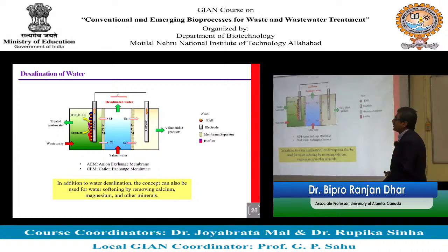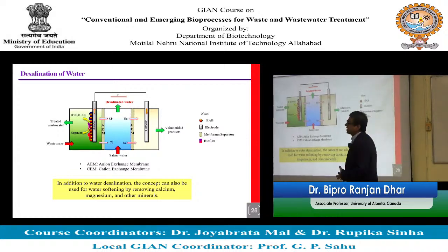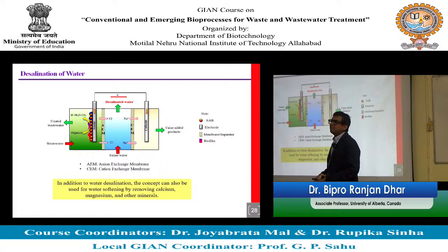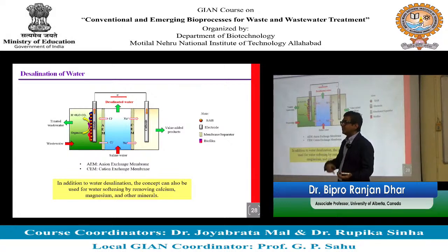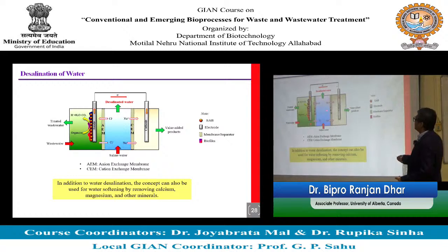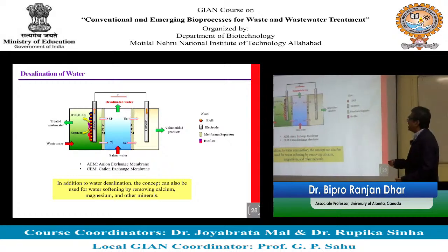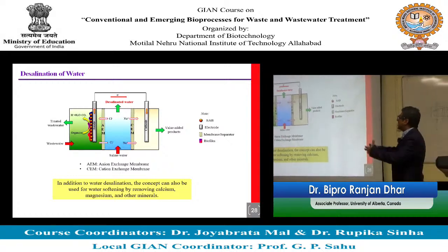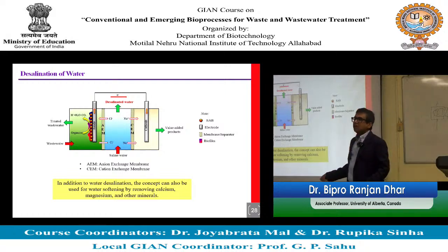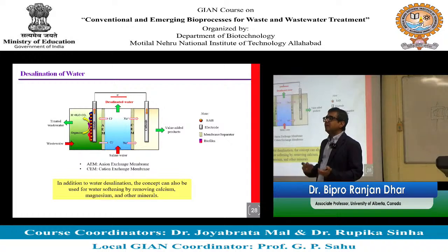But most of the time, the water softening process is done by using resin, and you use salt water to regenerate the resin, which is a common process. But researchers demonstrated that if we provide hard water in the middle chamber, we can get rid of the ions that contribute to water hardness, like calcium, magnesium and other minerals, and we can get soft water from the process. Okay.